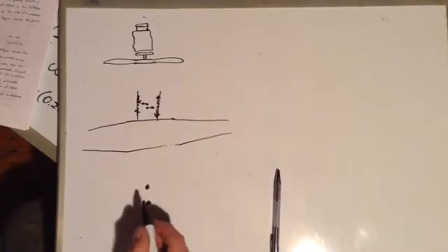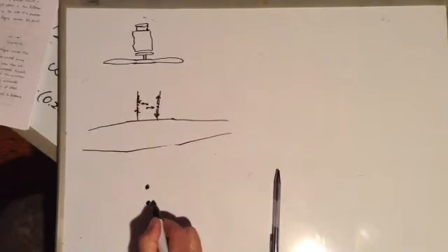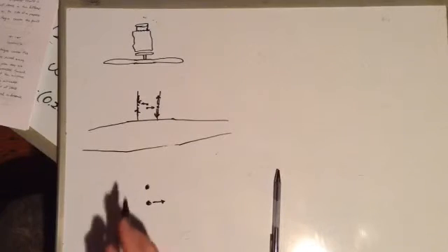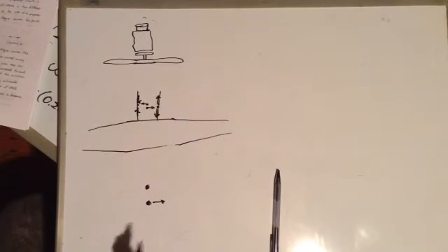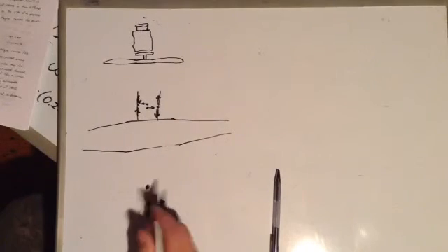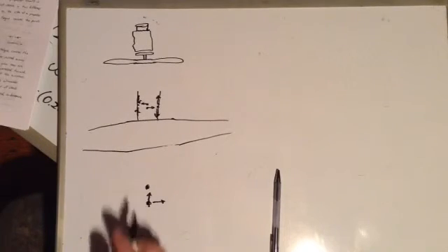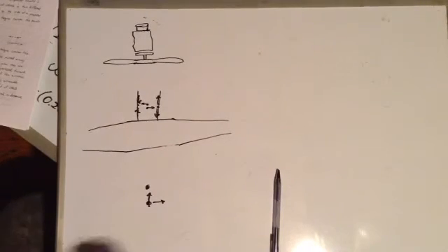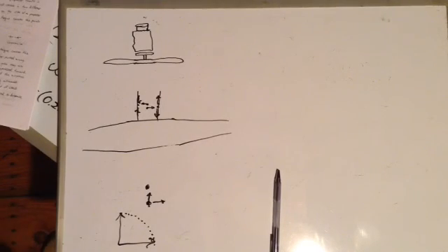So what we have is, here are two points. We have this point being sheared and wanting to go that way because of the engine turning the propeller, shear stress in the drive shaft. We have it in tension, being pulled this way when it's on one side of the shaft. We have it in compression, being pulled that way when it's on the other side of the shaft. Those alternate back and forth. So we have two different directions of stress. So the stress in each direction that is allowed is determined by the stress in the other direction. So in part 7 we'll talk about our quarter circle graph, which is used to determine how much stress we are allowed when we have stress in two different directions.